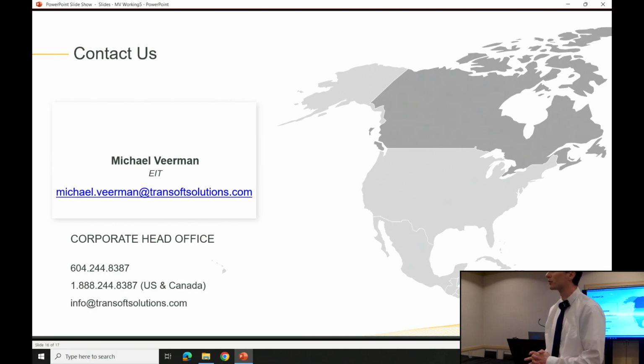The subsurface is something that's generated, and I recommend doing it at the end. In order to make the subsurface appear, it requires the terrain to be clipped out, and when that happens, it can't be undone. I recommend that as the very last step to the surface. You can't delete that clip, because it's based on that exact time when you clipped it out. Then you just apply the surface template to it. It's 2 minutes to do.